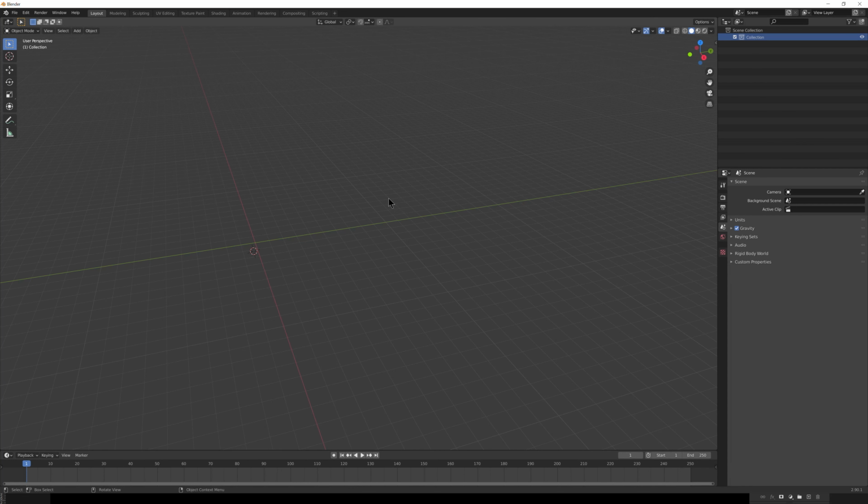So here I am in a blank, empty scene because I'd gone ahead and created one without a light source or box object, and then went to File, Defaults, and saved that scene for startup. Now I don't have to delete those objects when a new scene is created. I'm going to make sure that my model faces either down the Y positive or Y negative axis. If something is wrong, we can always come back in and rotate the model 180 degrees to work properly.